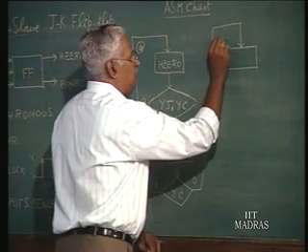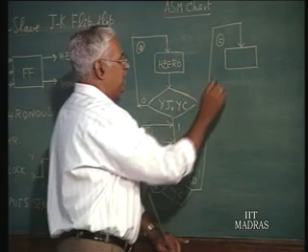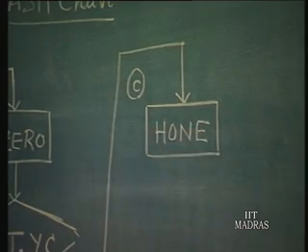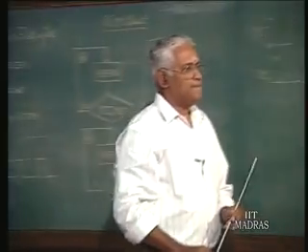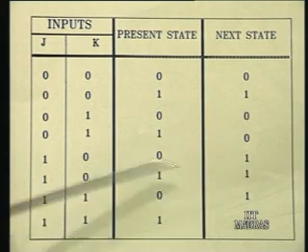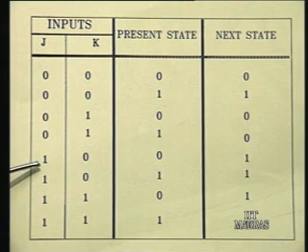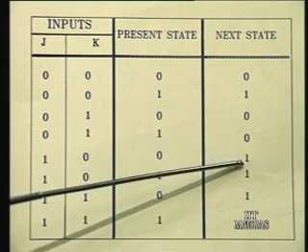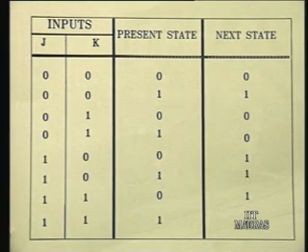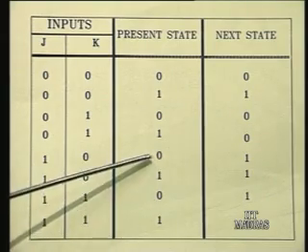There is a change in state, from B to C, and now the output that is generated is H1, which, with reference to the chart, corresponds to the next state being 1. Just see here, J is 1, okay, the next state is 1. So, J is 1, the next state is 1, correct. So, actually we are going from present state 0 to 1.